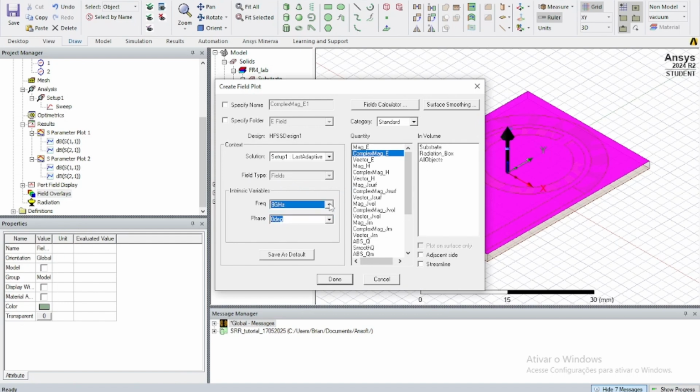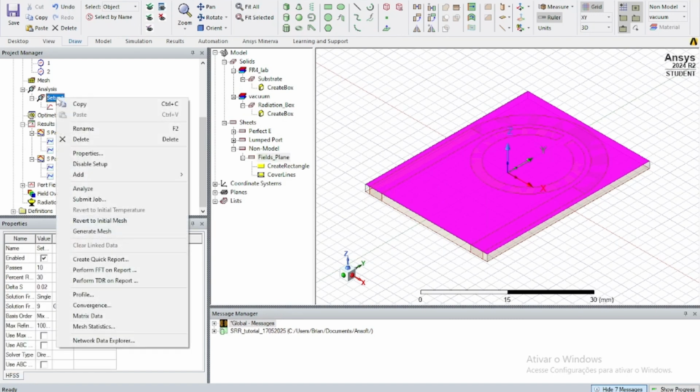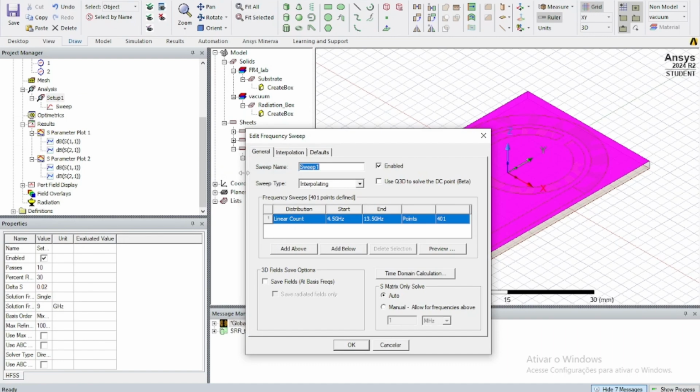Okay, so of course, something that you have to do previously is to create a single frequency sweep. So you have to create a new setup or a new sweep. Let me go here, frequency sweep, and then you're going to choose discrete and then single point, and you define it, for example, at our interest frequency, which is 1.52. Say fields, check.